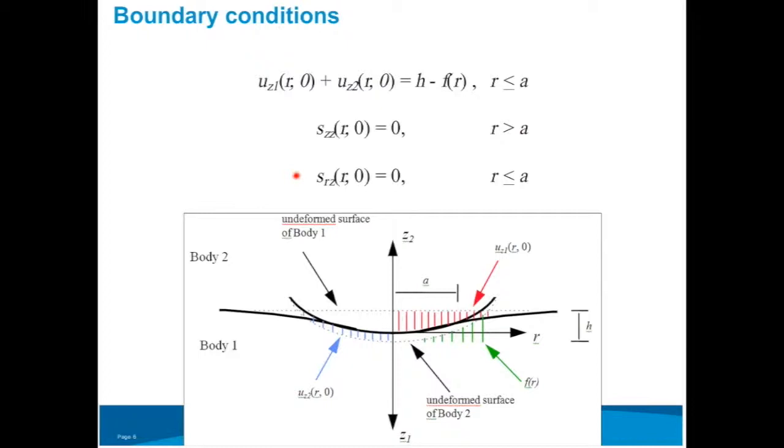I haven't gone into specifically in this presentation how this equation is applied when you have plastic contact. I think to some extent, Benoit is going to address that. But certainly, if you have substantial friction, you're going to get away from the applicability of this equation. And one of the ways that you get substantial friction is by using a very sharp indenter.